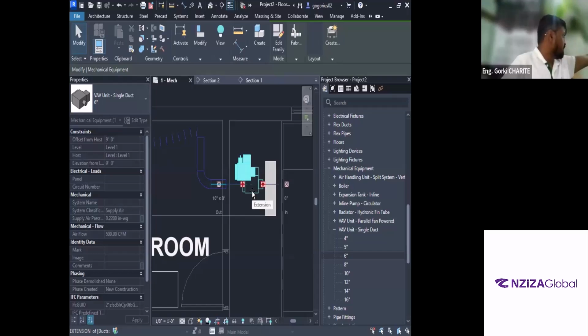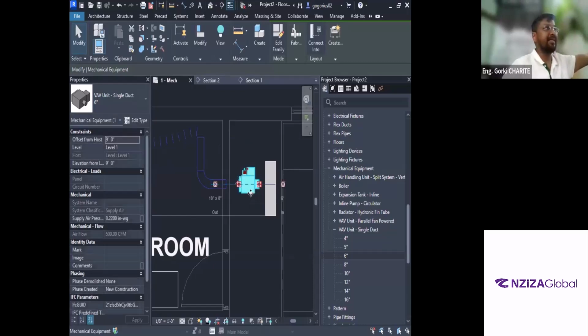duct over here. Okay. So if you hover around, Revit will automatically try to snap to the center of that particular duct over there. Make sense? Now you see that center dark line that shows up over here when I try to move the VAV box. So by itself it will try to align the center, at least the horizontal center. We'll talk about the vertical height center, but at least the horizontal center, it has aligned itself to it.